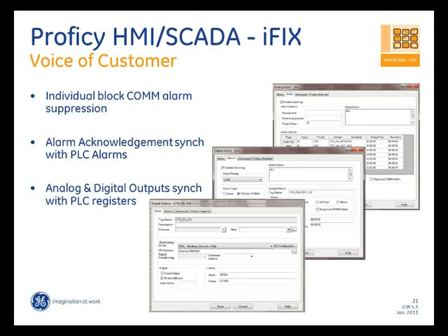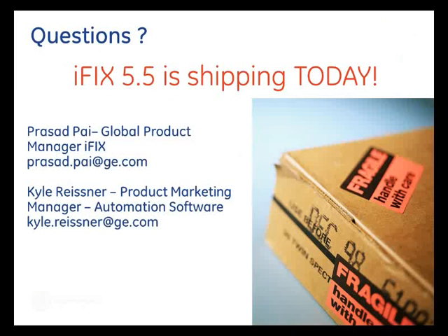So we made some changes to the way it parses that timestamp, and now you can use the SQL native driver as well with that. So those are some of the VOC functions that we put into iFIX 5.5. So I think that was my last slide, and I think I can open it up for questions.